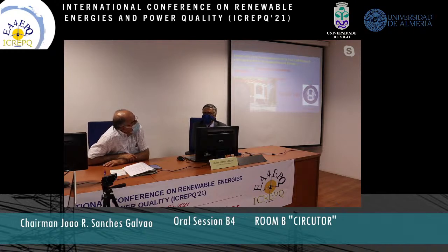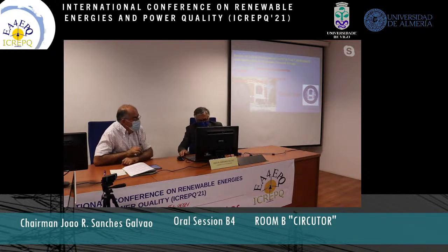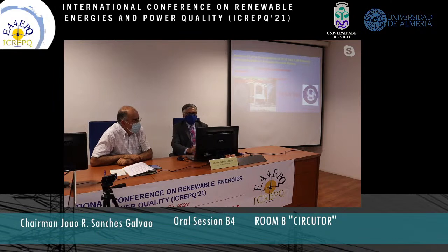If you don't have sufficient humidity, then we will not be able to effectively pass protons through the membrane, and if you have too much humidity, you could have a layer of liquid water on the membrane, and it would block the flow of protons. So it is very important to optimize the humidity, and that to me is one of the biggest challenges.